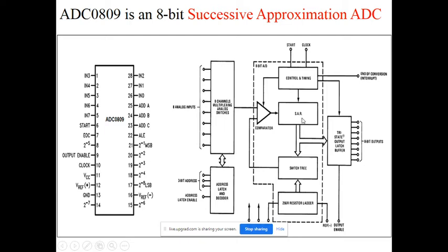Okay, then conversion is started, and before starting this conversion we are giving the start of conversion signal. Initially you are just connecting one of the channels to the ADC converter, then you are giving the latch signal. That time, whatever address, according to that one of the channels is connected. Then the controller will send one signal that is called the start signal. Then the ADC starts converting analog data into digital data, and for the conversion process it takes some time.